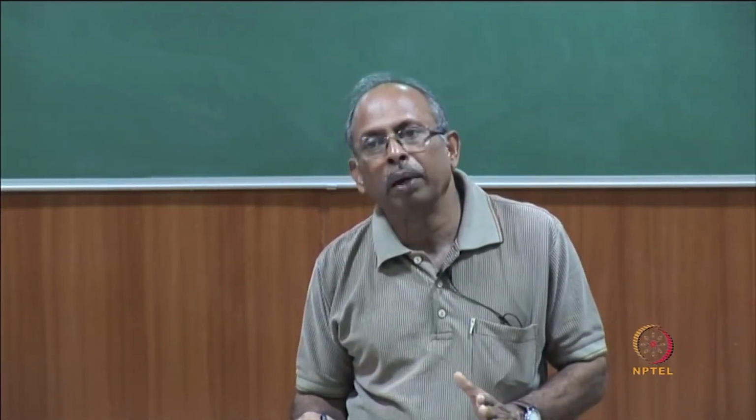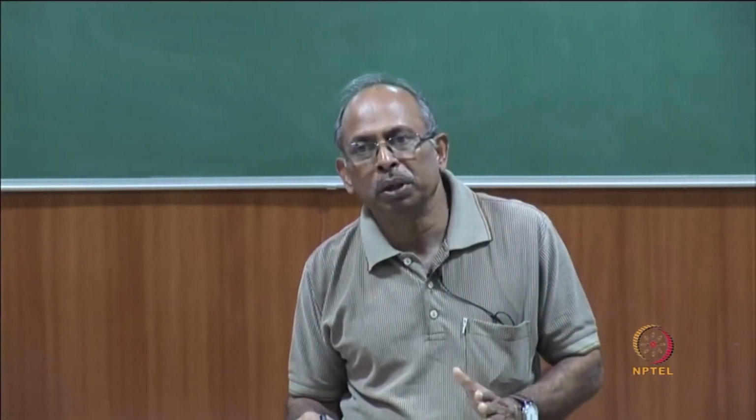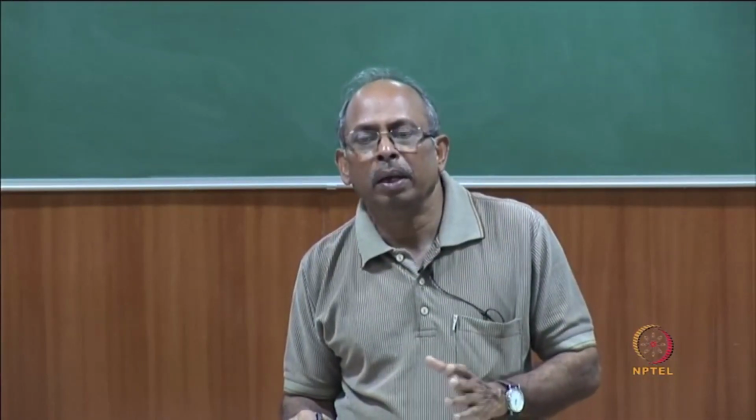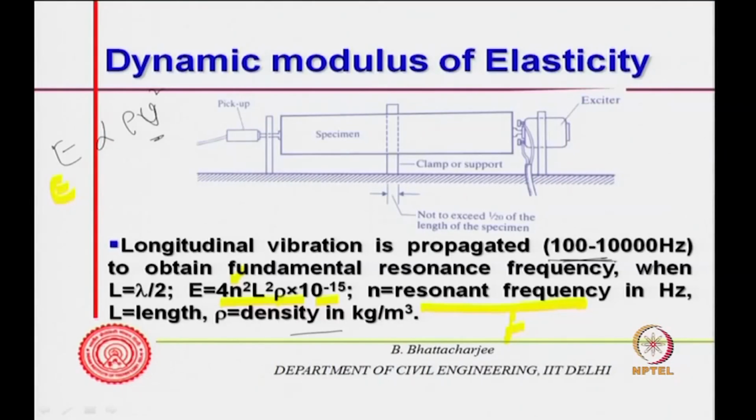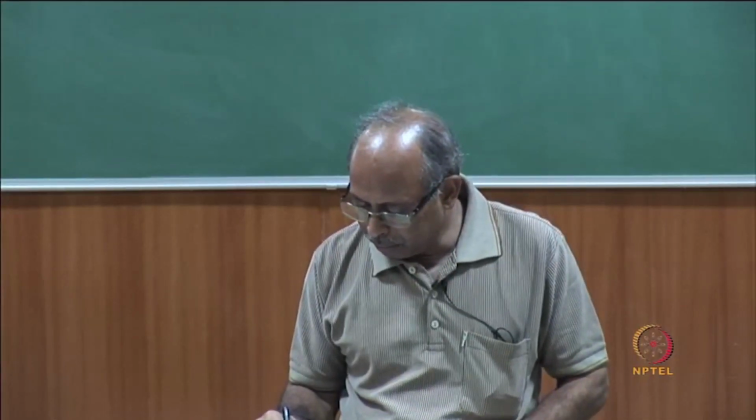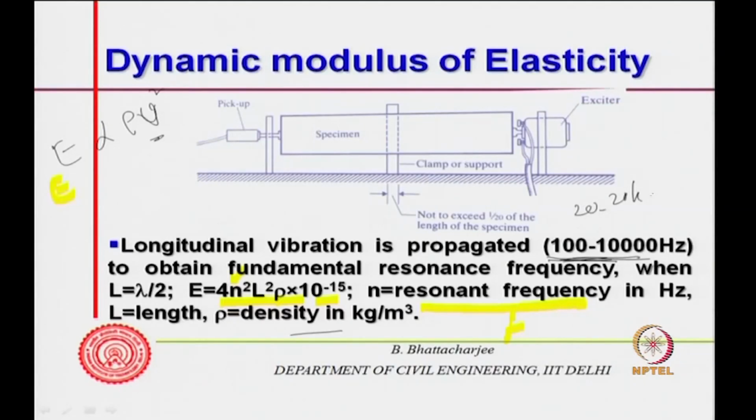First, what you do is impart longitudinal vibration or mechanical wave, so excite through acoustic waves or sonic waves from 100 to 10,000 hertz. It is actually sound, because sound is from 20 hertz to 20 kilohertz. So, it is not ultrasonic; this is actually sonic excitation you can provide, and then find out the modulus of elasticity from this.